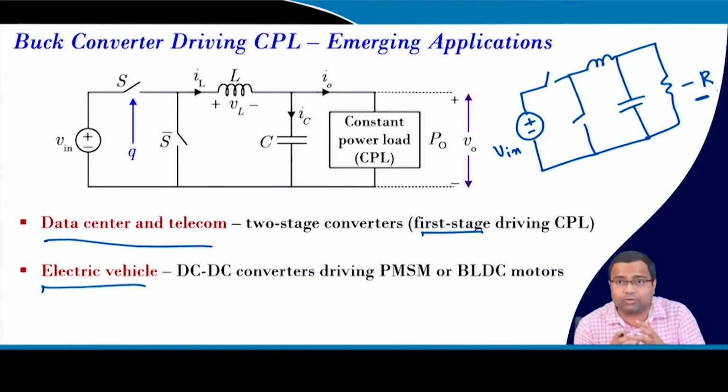We showed that if we use an actual two stage converter and simplify the second stage as a constant power load, there will be slight deviation, but the average responses are close. So, the constant power load will introduce a negative incremental resistance effect, and it will lead to an open loop unstable system.